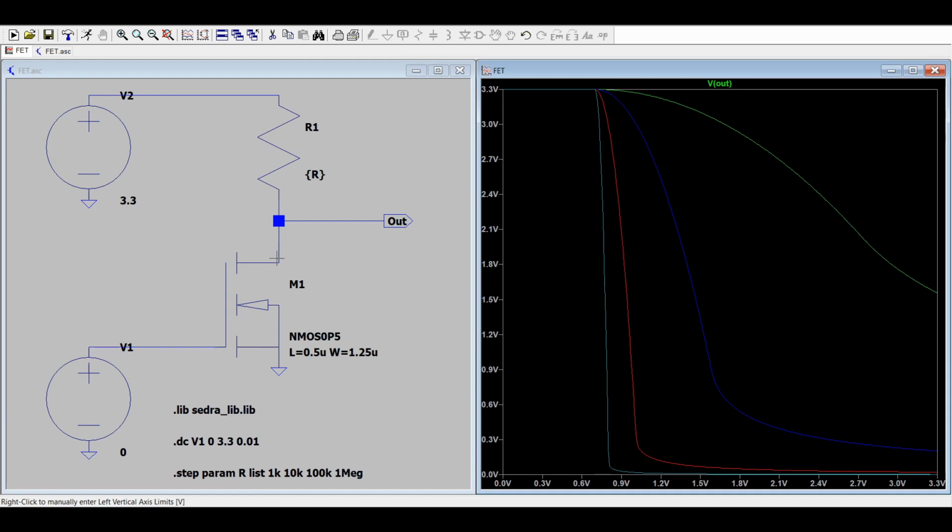What that means is that the resistance between drain and source goes from being approximately infinite, of course it's not really infinite, but approximately infinite, then when the gate to source voltage crosses the threshold, it starts to decrease down to reasonable values. And that decrease is fairly sharp. There's a sharp transition here.